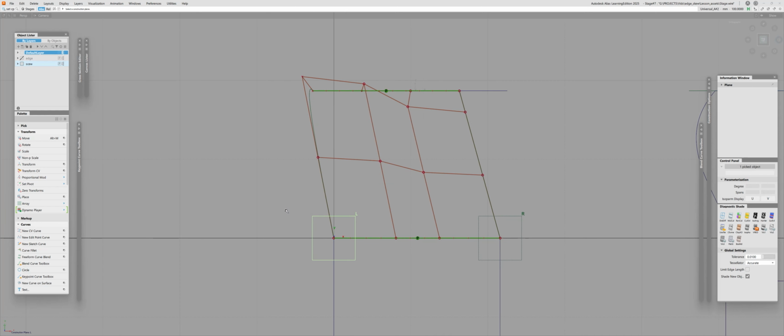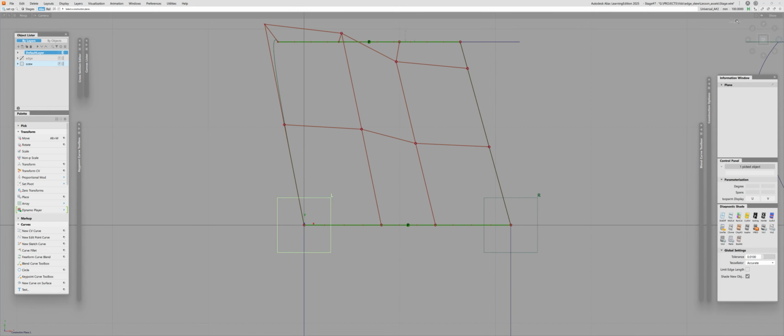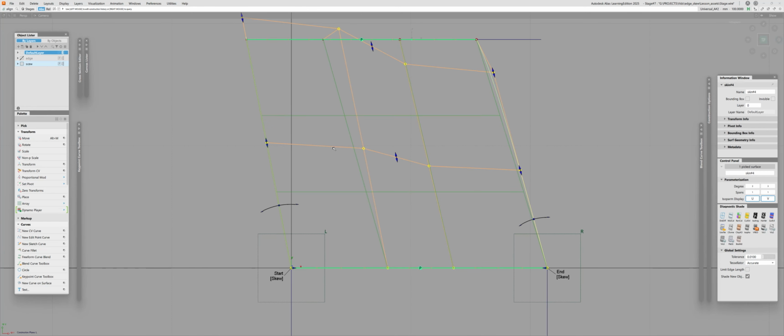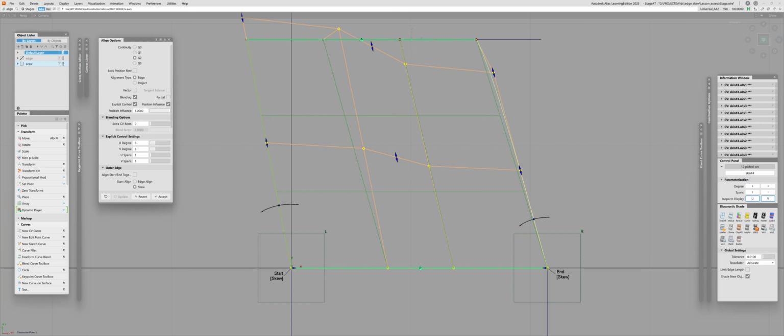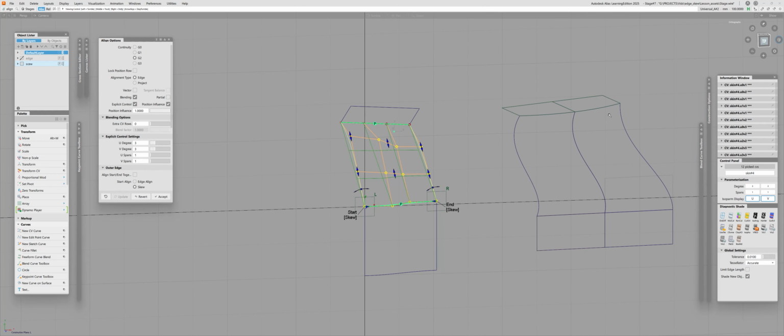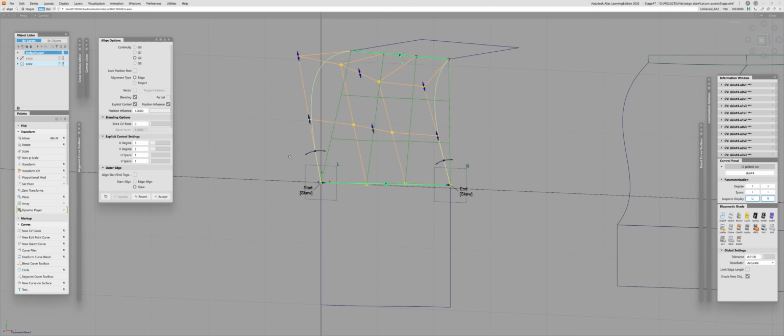If I activate this plane and look at this one, like that, you're going to see now it's following. This is the intended behavior of the skew align option. It maintains the boundary from the tangent plane of a surface you're aligning to. This is a very, very useful property of the skew align, and I will show you the next example here. But first, we need to cover the oddities of the skew align.